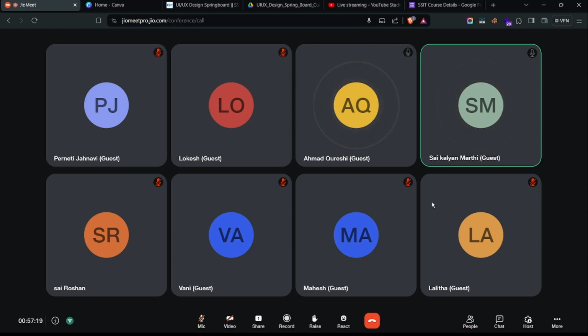For example, with Arduino you are not working on the controller directly; you are working on some software. Yes, sir. I'm working on test codes of controllers. If you are working on that, then you can find some board where you can understand the register mapping. So find some STM32 and start reading each peripheral. Go with each peripheral. Start with GPIO, then timers, then UART, then SPI, I2C, and buy some sensors to interact with them. In this way, you can learn better. This is my suggestion.